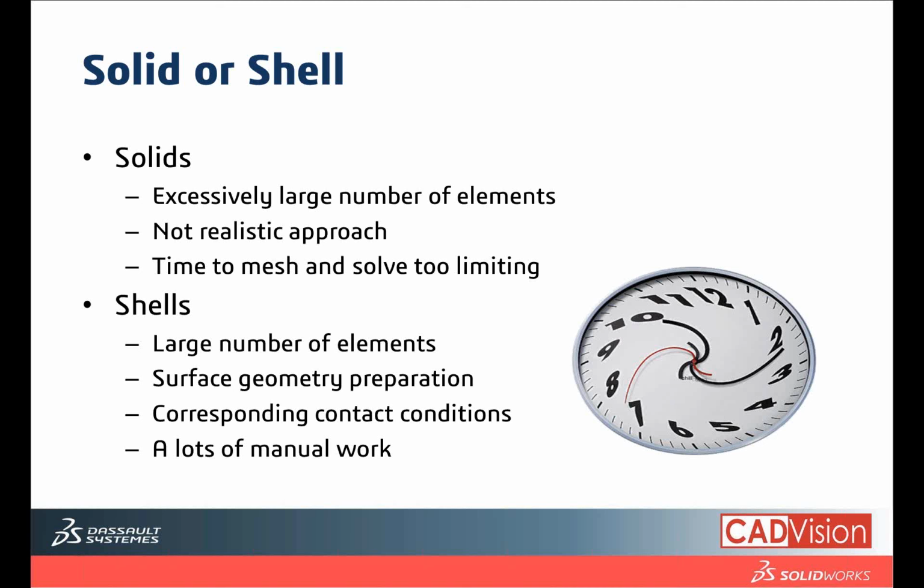As for shells, although they don't include that many elements, you still need to prepare all the surface geometries. You need to verify what the contacts between them are, and what the thickness of each of the elements is, so that they can be made into shell elements. So it's also time consuming, not in terms of solving and not in terms of meshing, but in terms of producing the shell elements to be studied.